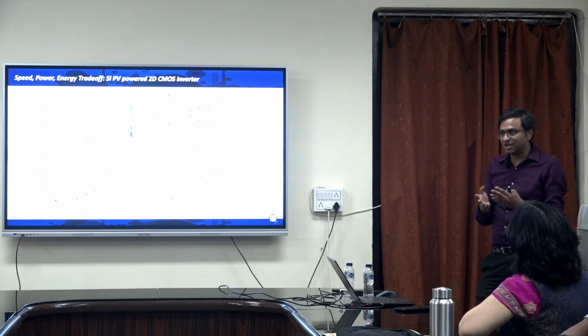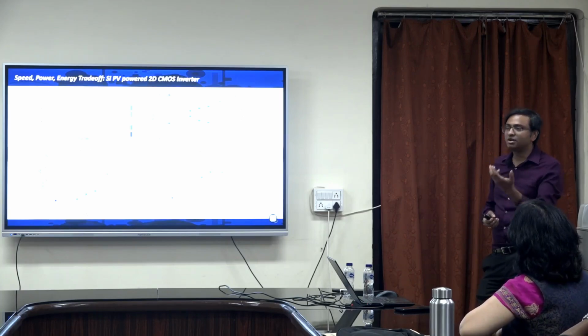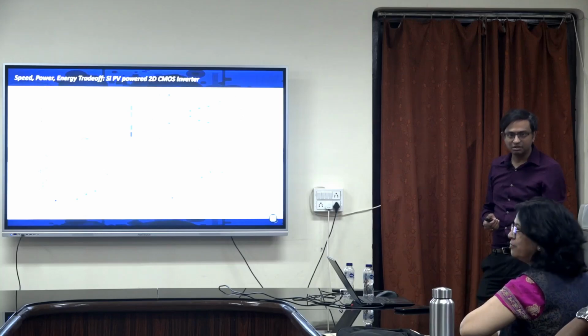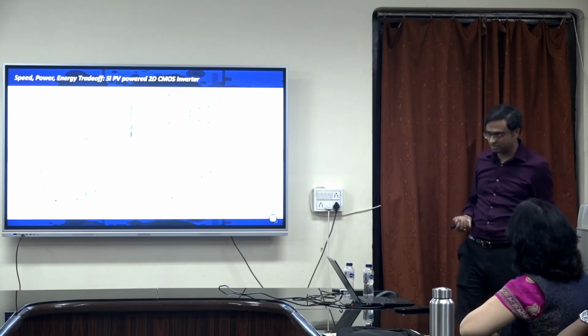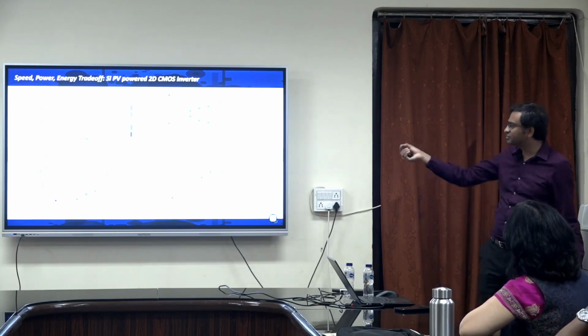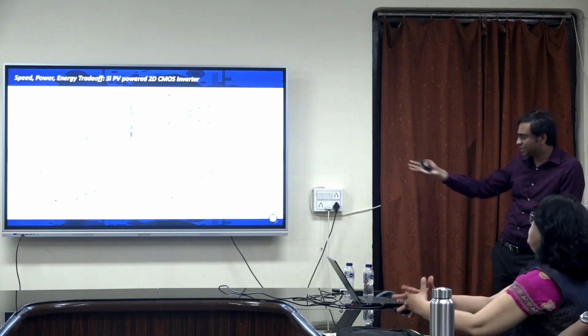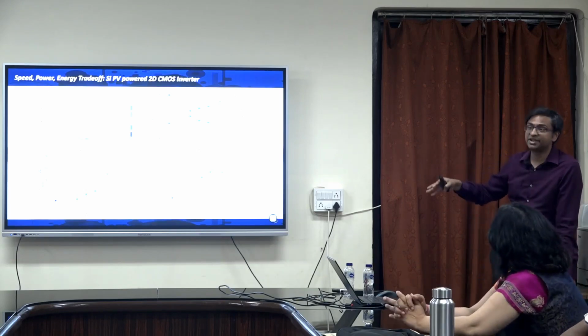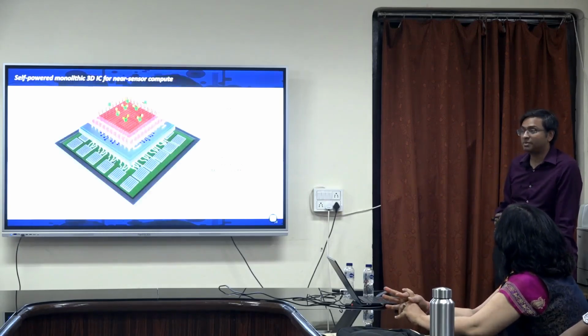That's why I'm telling you guys that the application is important, not just how good you can make your devices. So when you are monitoring, let's say, carbon monoxide in a room, do you need to measure it every millisecond? No, every second is good enough. That will be enough for you to then go and evacuate the building. So the requirement is milliseconds, or maybe tenths of a millisecond. Why should I need a device that has to work at nanosecond? No need. So I can use this kind of device for this application space, this IoT sensing.